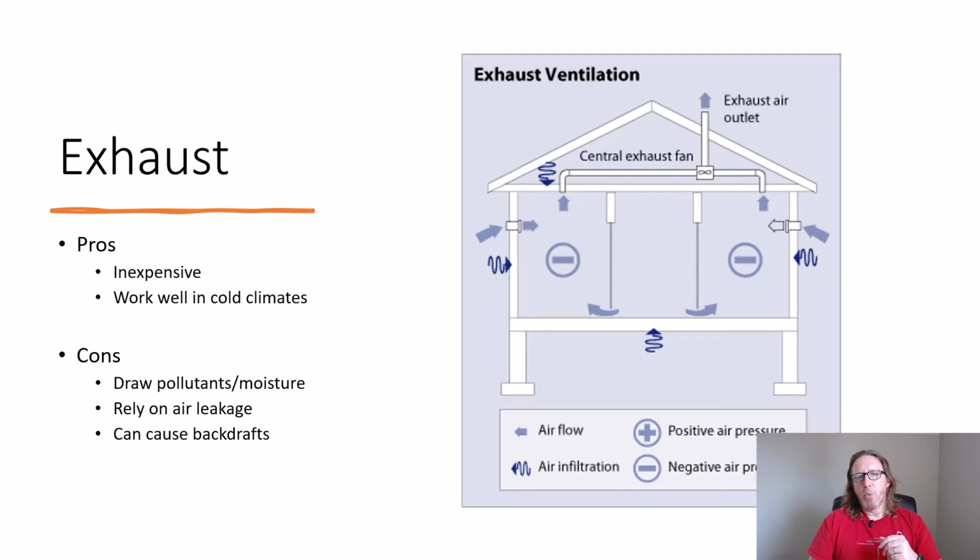So in other words, if I've got a fan or something like that pulling air to exhaust that air out, as they show here, I'm getting air infiltration through the walls, through the sill plate, through the band board or the rim joist, through the crawl space, through all of these areas, and none of these areas are being filtered or humidity controlled. So it is the least expensive way to move air through your home.